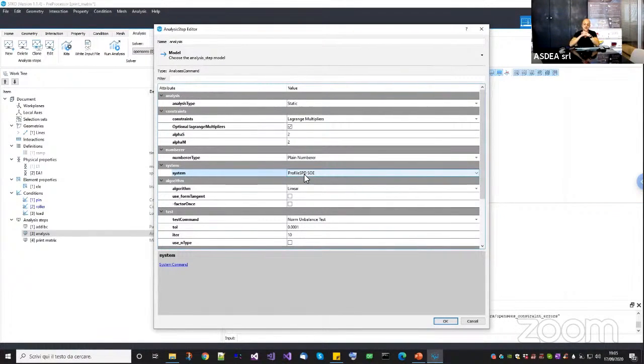This is fine, but a model is not always positive definite. It is positive definite when it is elastic or when it has strain hardening. When it has softening, it is not positive definite anymore because it has negative eigenvalues. When it has plasticity with non-associated plasticity, for example, for those of you who are in the geotechnical field, it is not symmetric anymore. So you cannot make sure that a model is always symmetric and positive definite, okay?